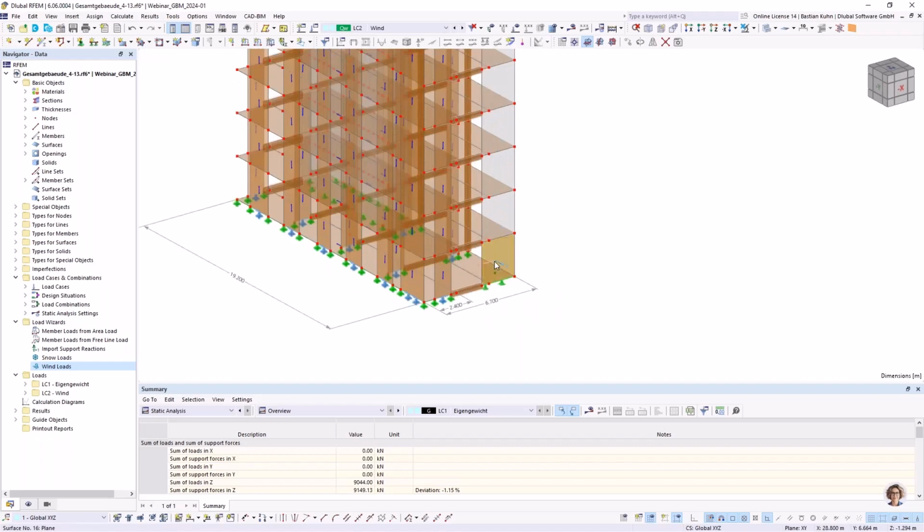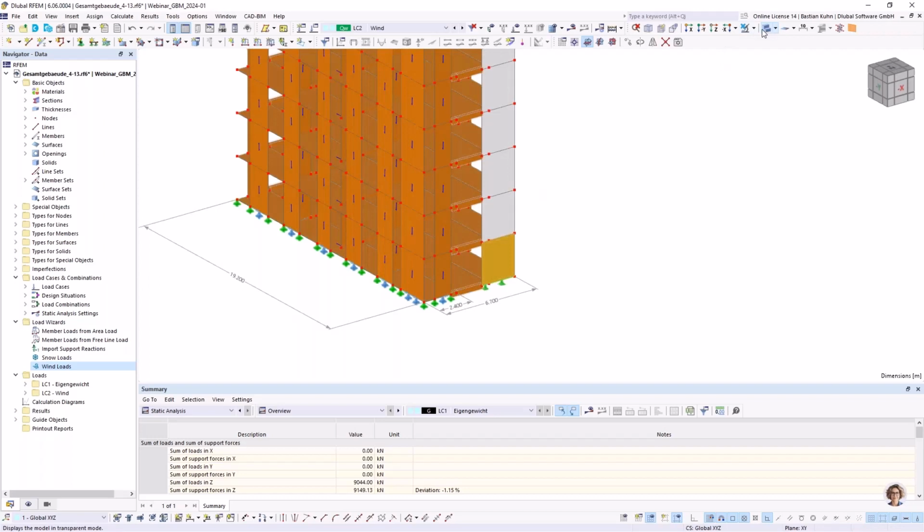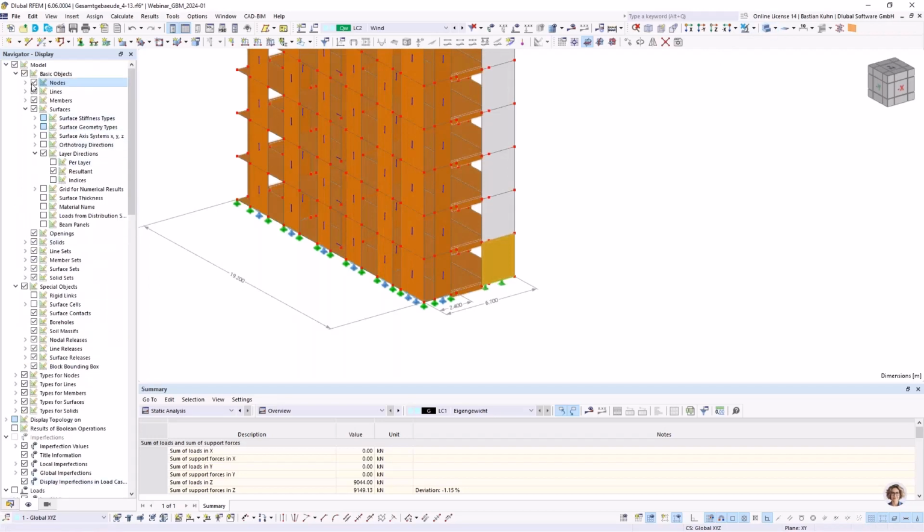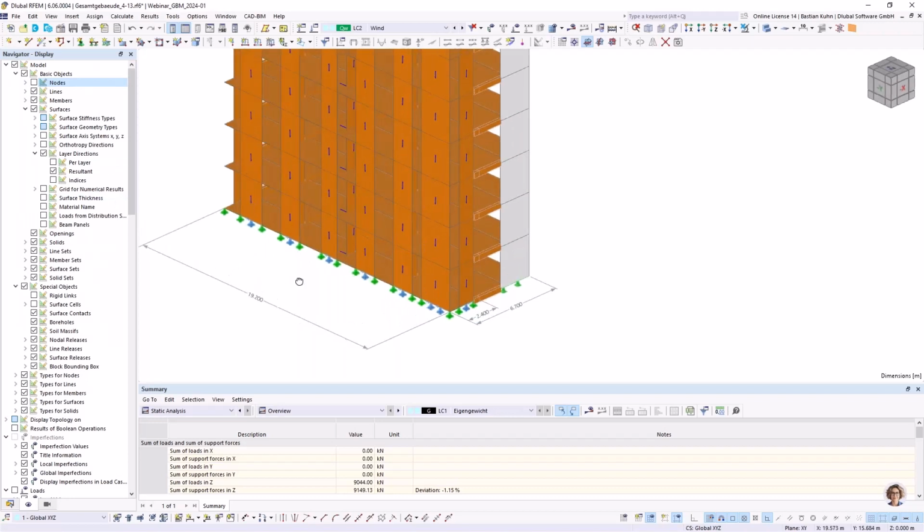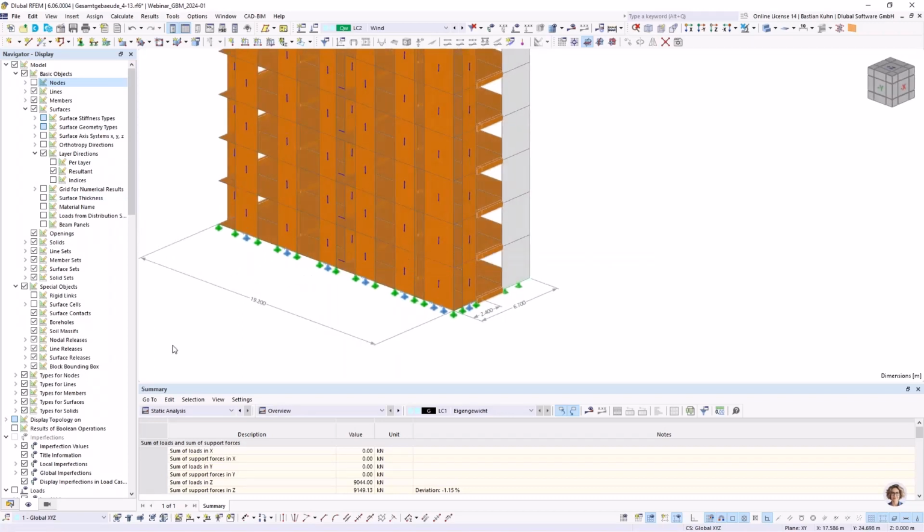Take a look at the slab or at the walls. Slabs we did. Maybe if I put this on and we can get rid of the node, it's looking a little bit better. The stiffness direction, I don't know if you saw that when I mentioned it on the ground. I have an option for the CLT plates to show the resulting stiffness, and usually walls in CLT plates, you always put the stiffness direction vertical, and on slabs, you put it horizontal. That's what this blue check should tell you.